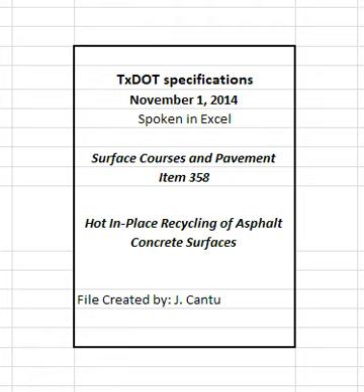3.1 Processing equipment. Provide equipment that is capable of a continuous single-pass, multi-step operation, including heating, milling, introducing recycling agent, virgin materials, or HMA, if determined necessary, mixing the reclaimed material, redistributing the recycled material, placing the mix and leveling it with an asphalt paver or paving screed, and compacting the mixture, that meets the following requirements.